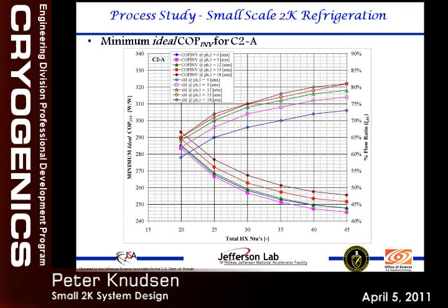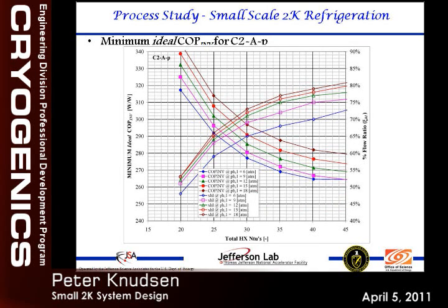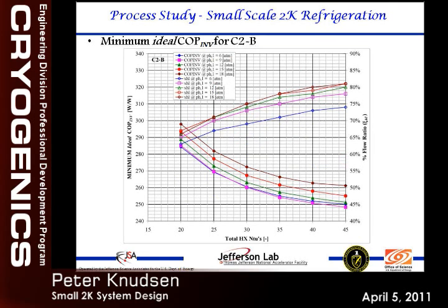These curves up here correspond to this axis, and this is the flow ratio, that high stream to low stream flow ratio. So at that optimum point, what is the flow ratio? And we can just go through it. They are all pretty similar. These are ideal, one for the integrated purifier, and this is the ideal COP inverse for the one that has the heat exchanger that has the varying injection point.